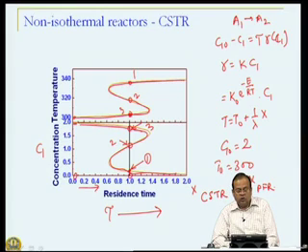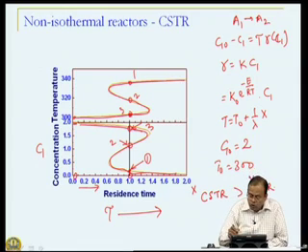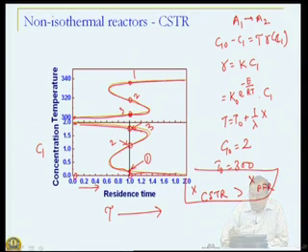So, the rate of reaction also decreases in a gradual manner, compared to CSTR. In CSTR, the drop in concentration from entry to exit is almost instantaneous. Therefore, the reaction rates are very low, whereas in a plug flow reactor, there is a gradual decrease in reaction rate. So, in general, reaction rates are higher than in CSTR, and therefore, we have a higher rate of reaction in the plug flow reactor, so better conversions.